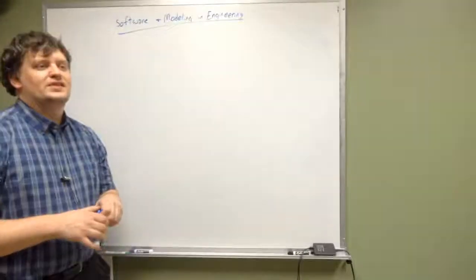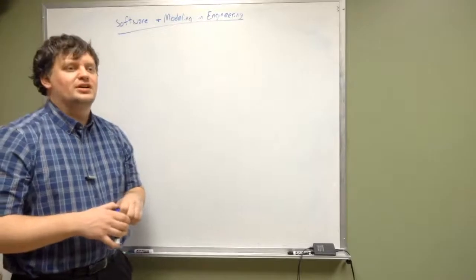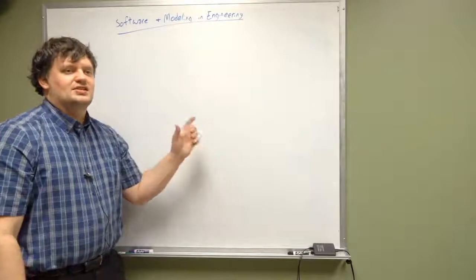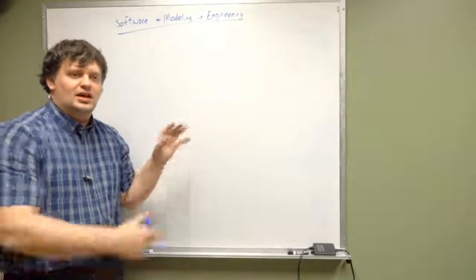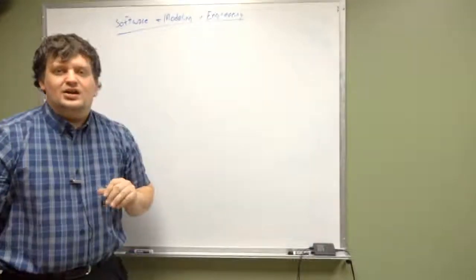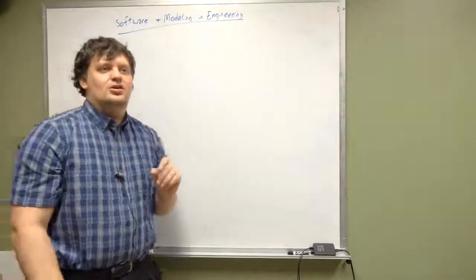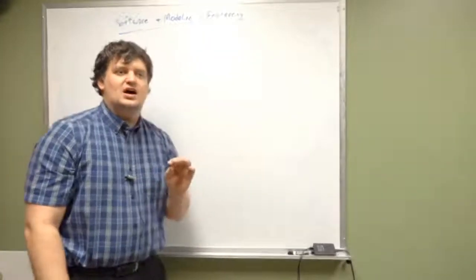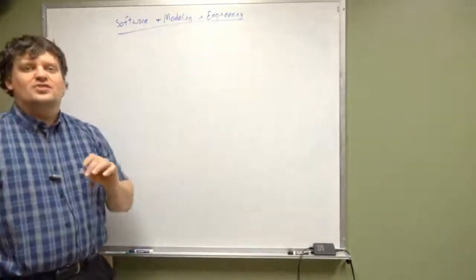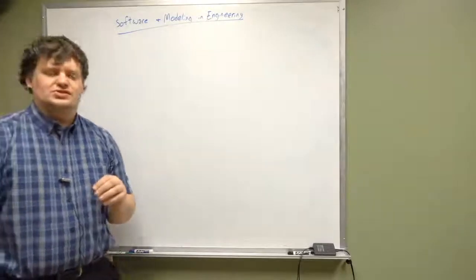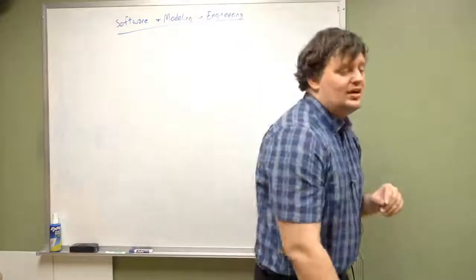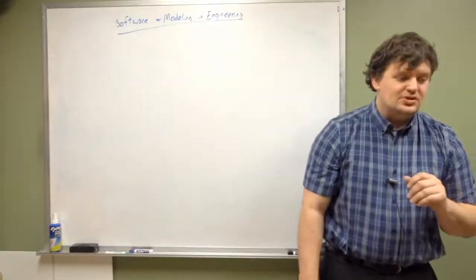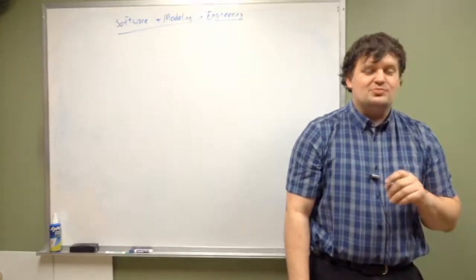I want the dimensions of the aluminum brick to be made such that it is 3 inches wide, ½ inch tall, and 3 feet long. I want the top surface to be milled. On all of those dimensions, I would like to have a tolerance of plus or minus 0.025 inches. Okay. Now I can tell that all to you,